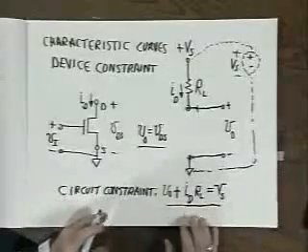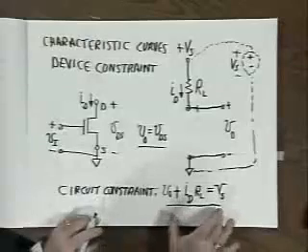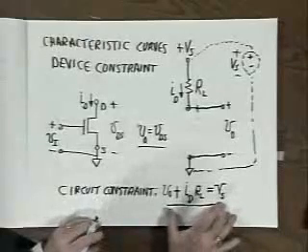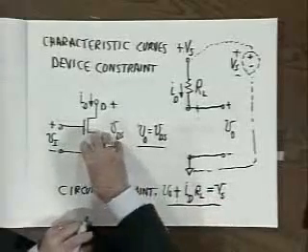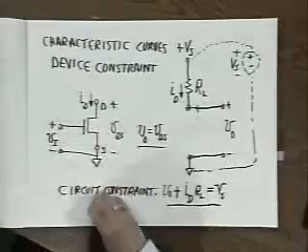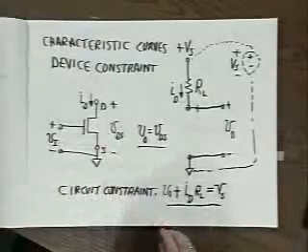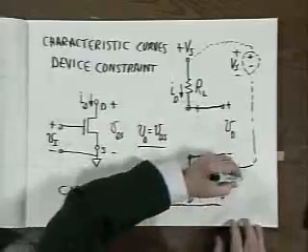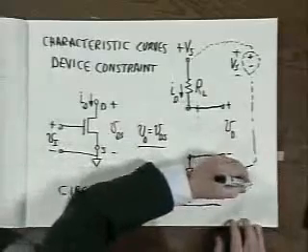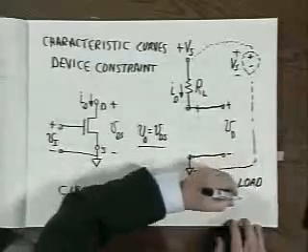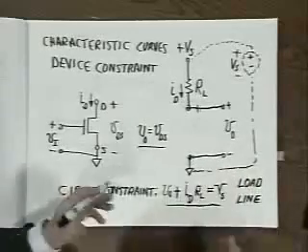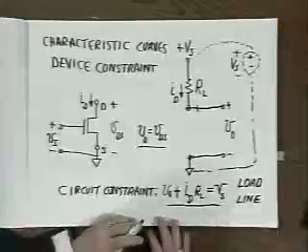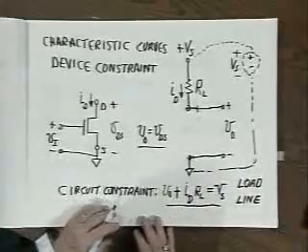And to solve this problem, what we can do is take this linear relationship representing the circuit constraint, and impose it on the nonlinear characteristics. On the nonlinear characteristics, it is commonly referred to as a load line. And while I'm illustrating it here in terms of a MOSFET amplifier, the concept of load line is extremely useful and comes into play whenever you're dealing with nonlinear elements.